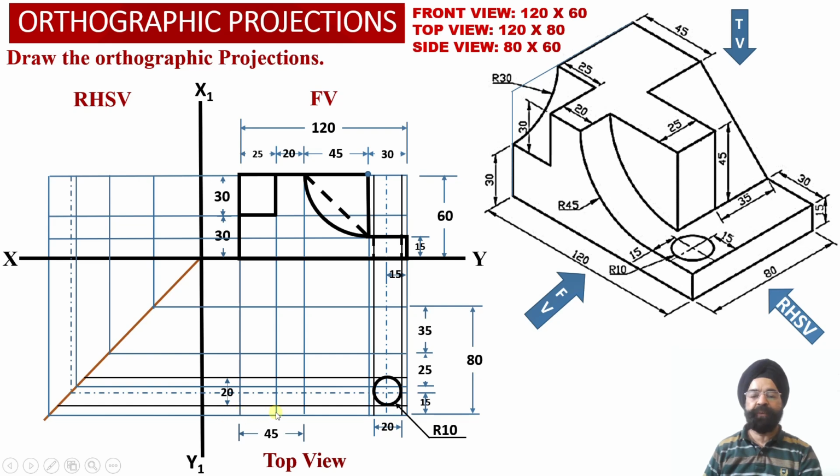So this is the front face of the solid. So from the front face of the solid, we are going to measure this radius as 30 millimeter, and at a distance of 30 millimeter from the front face, we have drawn a horizontal projector line into the top view projections, and we have transferred this horizontal projector line appropriately into the right hand side view projections over here.